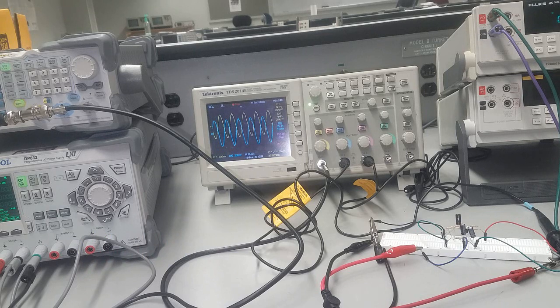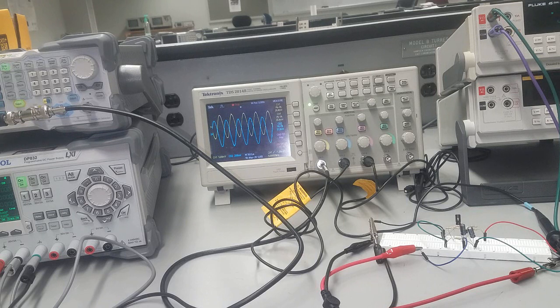Originally the design should be RS of 10K and RD of 17.7K. We said let's be conservative, assuming the gain was initially going to be lower, so we chose the value of RD to be 20K. This way we can get a higher gain, and hopefully a gain of 50 plus or minus 20%, so anywhere from 40 to 60 volts per volt.